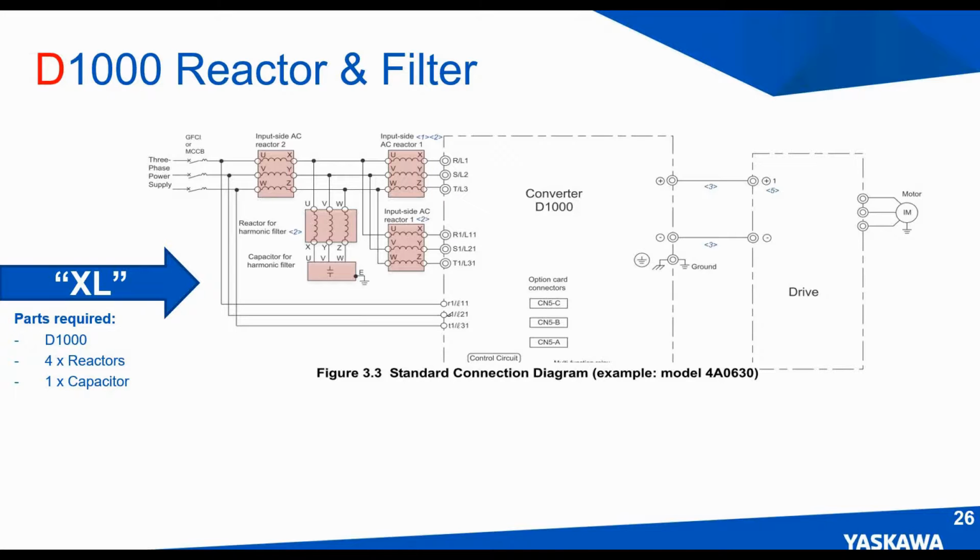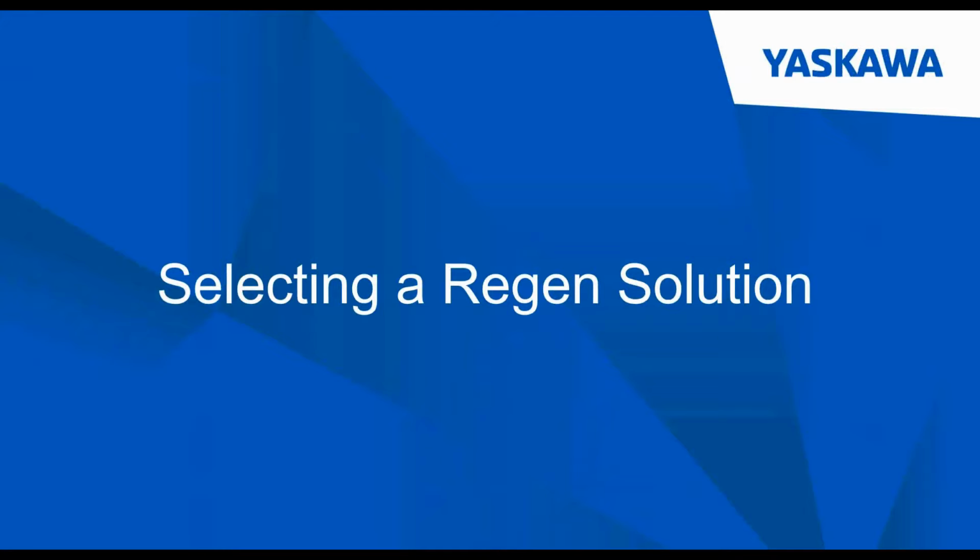One last time, let me point out those phase detection circuits. They must be phased correctly, so your incoming R lead must be tied to little r. Your incoming S lead must be tied to little s, so forth and so on. OV and OC, as I mentioned, can occur if it's not connected properly. Just imagine trying to regenerate back on the line onto the wrong voltage supply. It's going to easily create an OV condition or an OC condition.